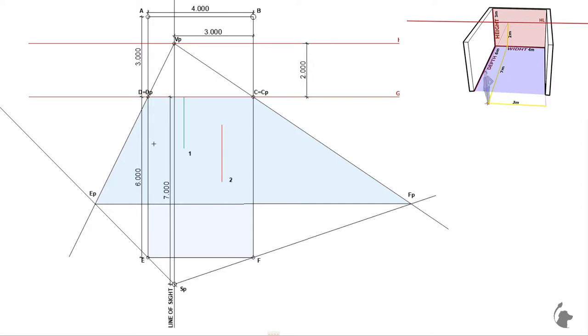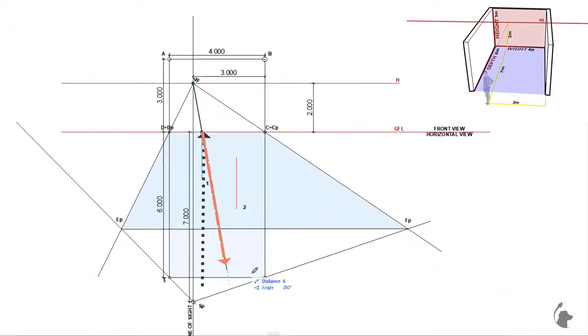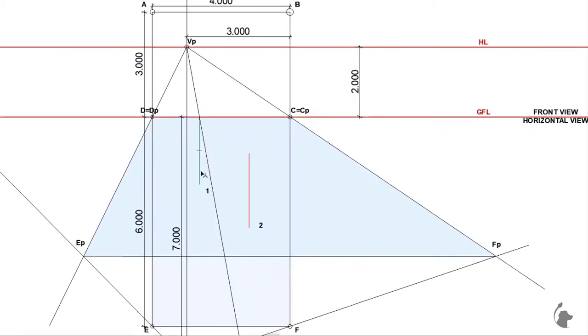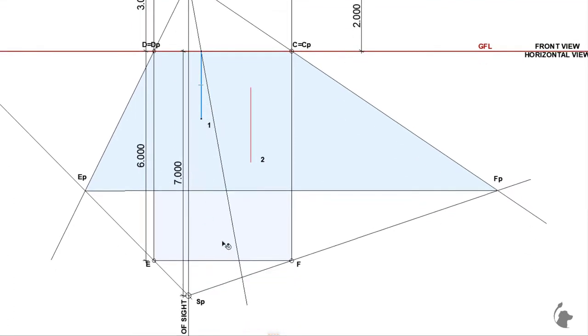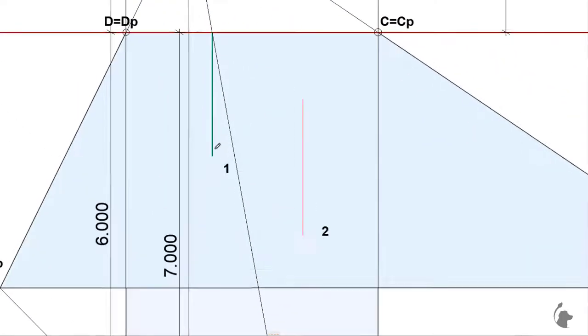Let's see exactly how this happened. Every graphically vertical line from the horizontal view is in 1 point perspective, a line coming from the vanishing point, because it's a line going straight forward away from us. These two sidelines are not magical, meaning that what we've just done with those measurements, we can do with any random line in 1 point perspective. Let's draw 2 more vertical lines in the horizontal view, just completely random, and name them 1 and 2. We'll make the second one not touch the ground floor line.